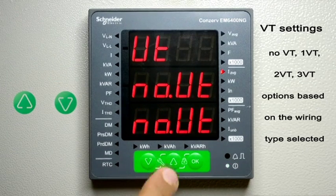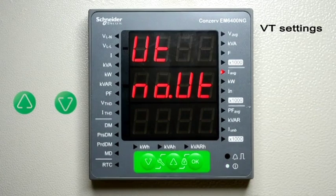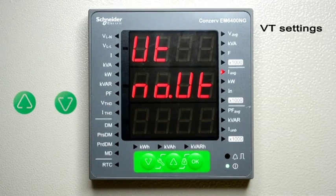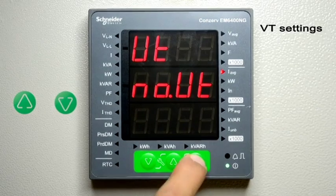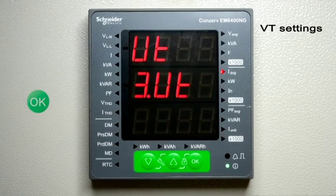through the options. Voltages of up to 480 volts line to line in category 3 installations and up to 600 volts line to line in category 2 installations can be directly connected to the meter. Voltages above these values, for example in MV and HV systems, should be connected to the meter through voltage transformers. For example, let us select 3VT configuration.